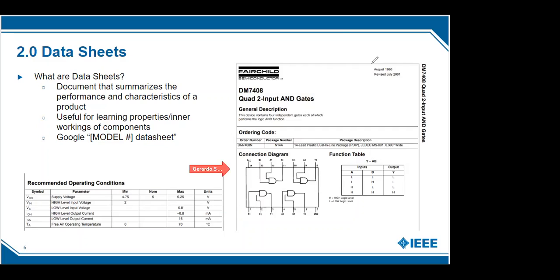All right, there's an arrow, just a red arrow pointing there. Where that red arrow is pointing, that's pin 1. So you would start from pin 1 of your IC chip and then go down 1, 2, 3, 4, 5, 6, 7. There's 7 pins on this side for this chip, meaning there's 14 pins in total.